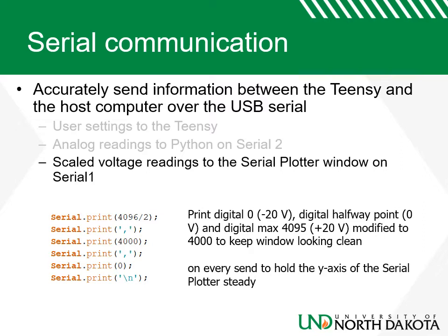These values are printed on every send, and this holds the serial plotter screen steady. This modification to the max digital value was only done on the serial plotter. The GUI screen, since it was more customizable, was kept to the more accurate value of the 4095 max.